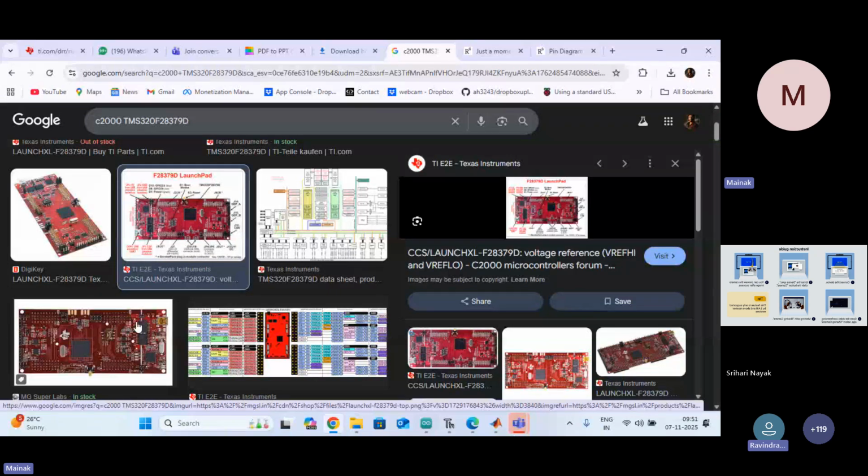And that is the same for Arduino microcontrollers also. You can't upload the code at the same time, you have to open the TX and RX pins. Okay, we have to open that and then only we can upload the code. Yes.